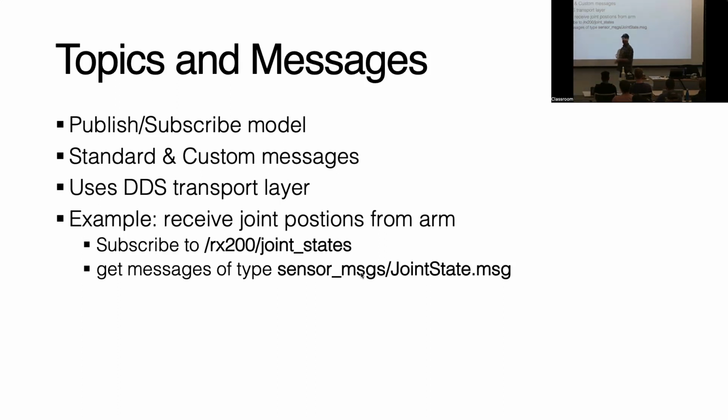And then whoever else wants to use that data will subscribe to the topic that those messages are being published on. And whenever a message is published on a topic, I will consume that message and then do something with it, all right? And so we're passing messages all over the place between different nodes all the time. And in this case, ROS2 uses DDS as that transport layer.